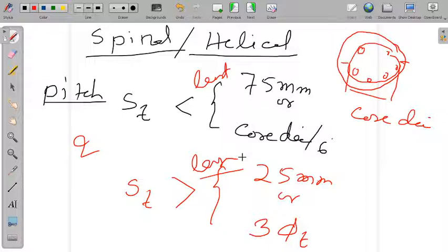For that purpose we have to go to the code book, clause number 39, limit state of collapse: compression. Here the minimum eccentricity is given in clause 39.2. What is said? All members in compression shall be designed for the minimum eccentricity in accordance with clause 25.4. Where the calculated eccentricity is larger, the minimum eccentricity should be ignored.